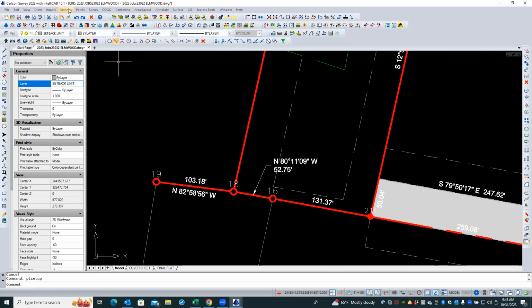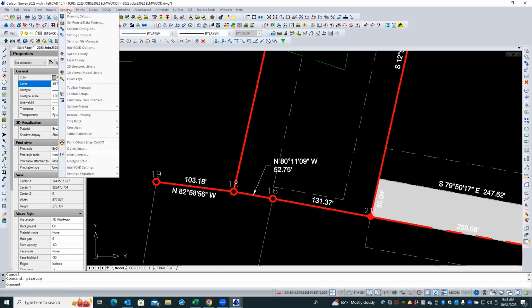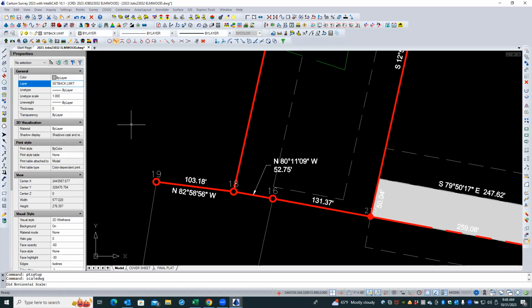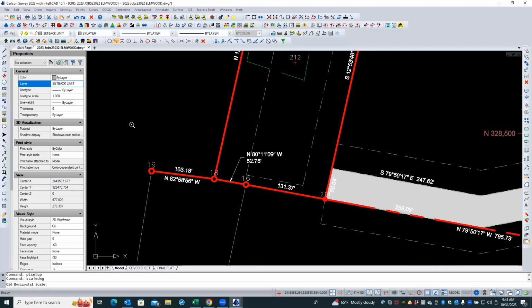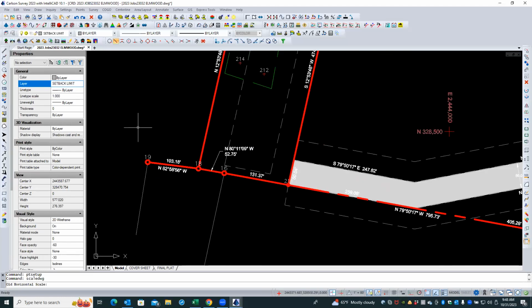Now I know where this is. It's not on the points menu. It's on the settings menu where it says rescale the drawing. See, and look at the bottom of the screen. It says globally resizes selected text, symbol, and block entities within the drawing. So if I say rescale the drawing and it says selected, so what's my old horizontal scale? Well, no, there's the difference.